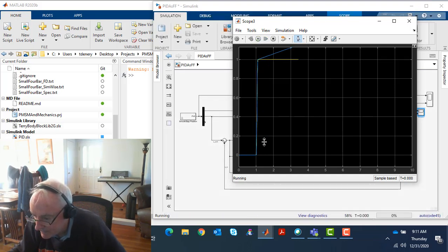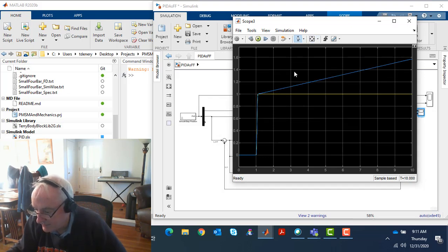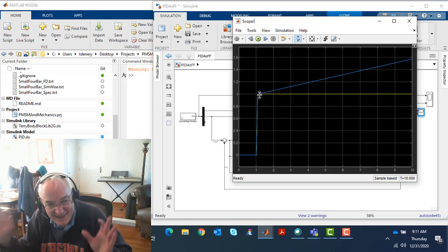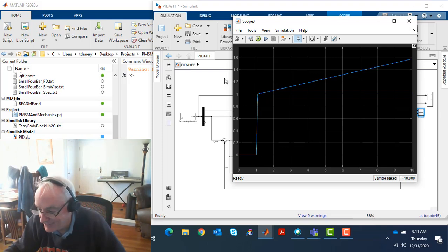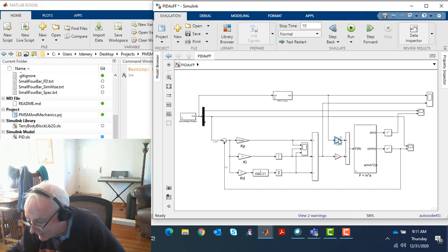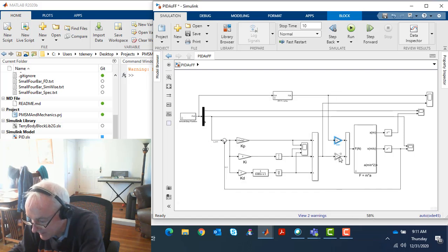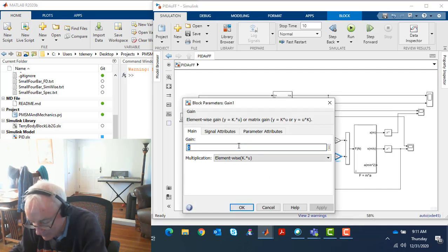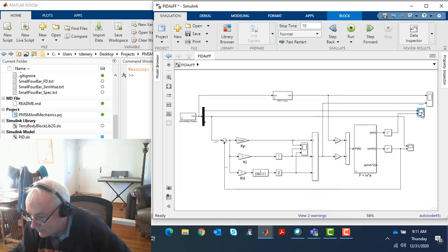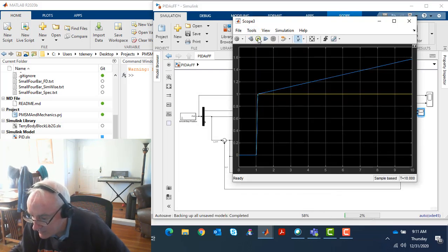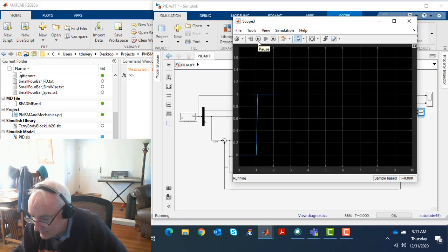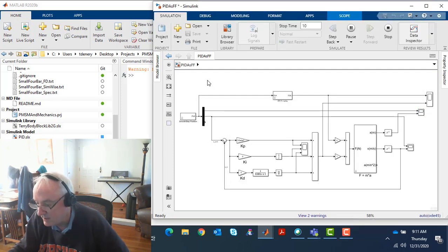And yeah, this is the remarkable thing of feed forward. It gets you through that transition, great. But when you get to the finish line, things aren't exactly right. And so then you go in here and kind of do it the other way, which is essentially PID, doing both feedback and feed forward. And we hit run on this. And again, it does it beautifully.